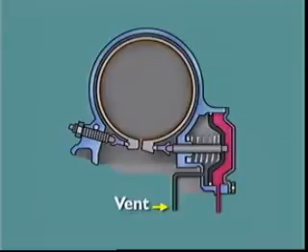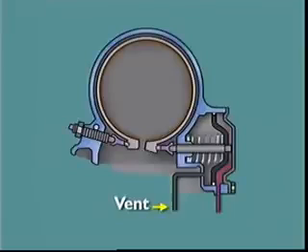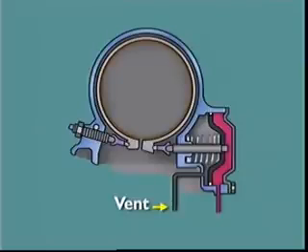When this fluid is dumped or exhausted from the supply line, the spring returns the piston, and the flexible band springs back to its released position. In a pressure release type servo, the band is applied in the normal way by fluid pressure acting on the piston head. However, this fluid is not dumped to accomplish band release.